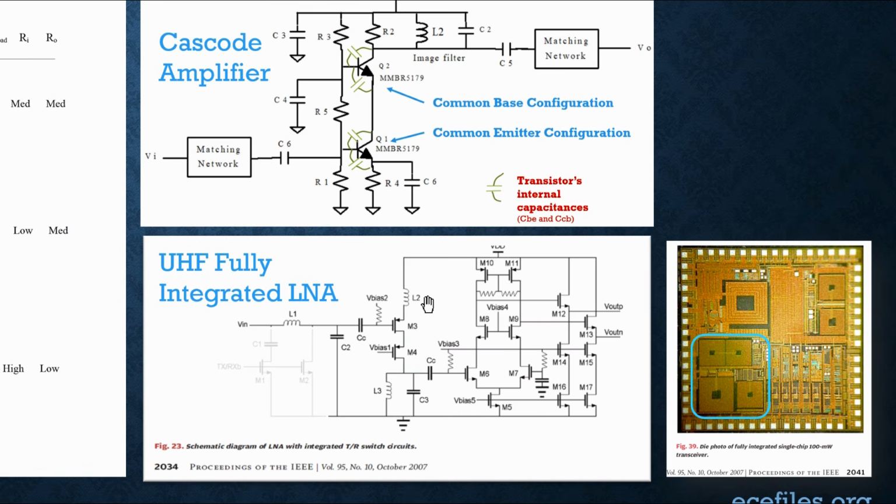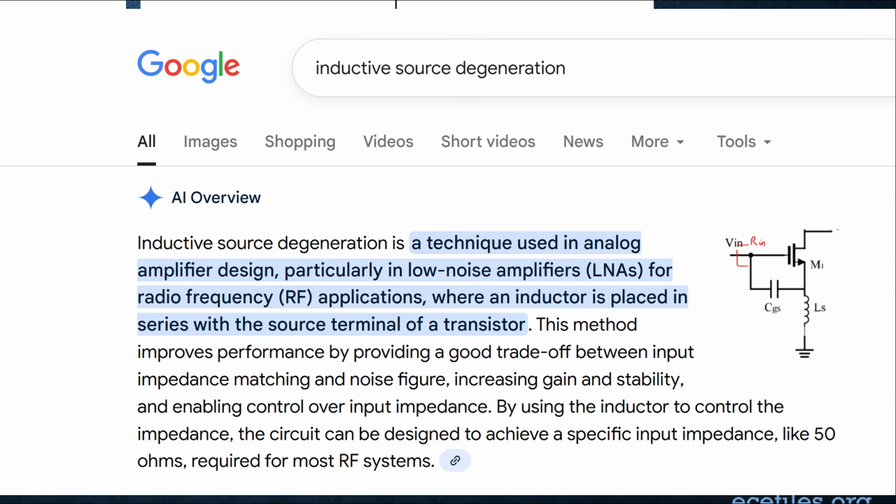What they don't often talk about, but is perhaps more important, is that this inductor here will help get you a much better noise figure, because noise currents in this transistor will come into L2 and see a high impedance, and they'll generate a voltage which then comes back into here, and it cancels the current that started all of that. It's very confusing, but it works. So in a nutshell, L2 is a trick to get a better noise figure.